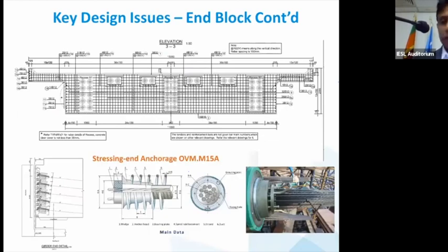Again, coming back to the in-block design, what I want to emphasize is these geometrical clearances. You have to put a lot of effort here just to make sure the jacks will fit. If the jack won't fit, it's a disaster at the last stage.